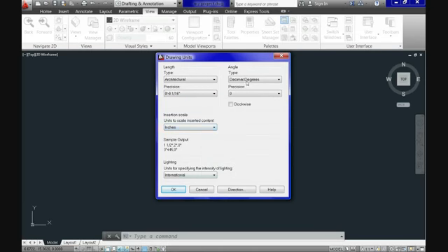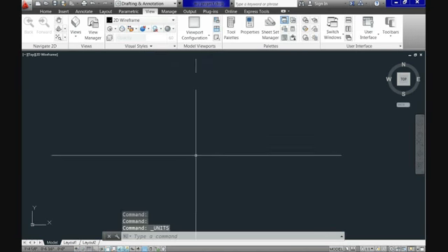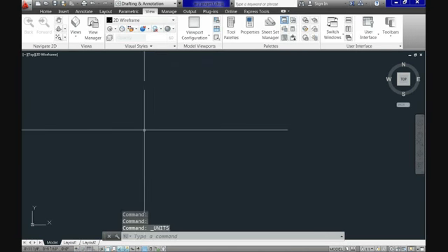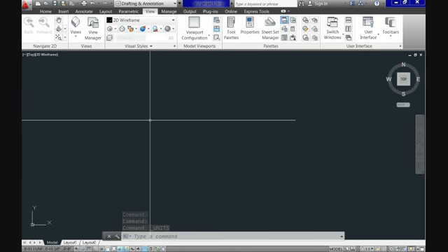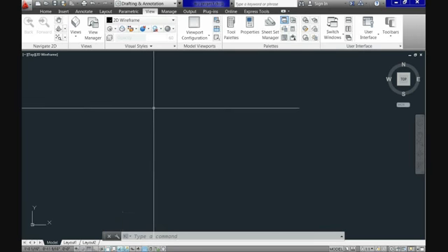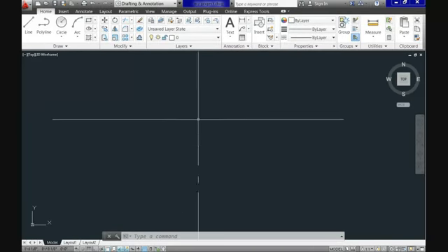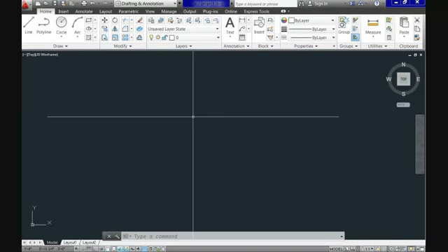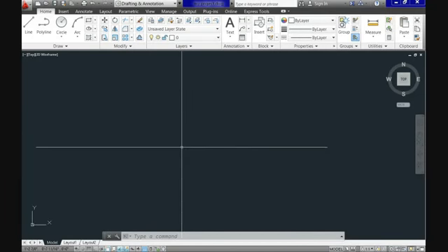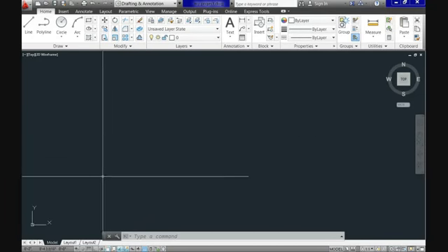Go on your own and work with it. So let's put it for us architectural, let's leave it like that right now. And from now on, whenever you specify which size, if you click line for example, it should be input in AutoCAD in feet and inches because you selected the units of measurements as architecture.